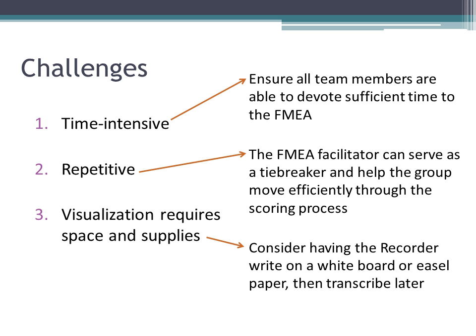The group will repeatedly determine failure modes, list causes, assign RPNs, and so on. So my advice to you is that you ensure a good amount of time is blocked off for the FMEA. All team members should be available for that half-day or whole-day session in order to complete the analysis.